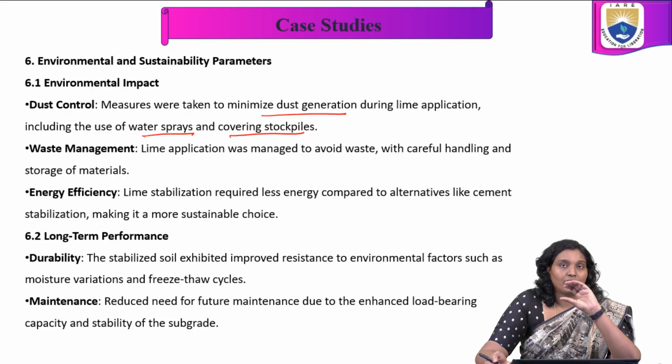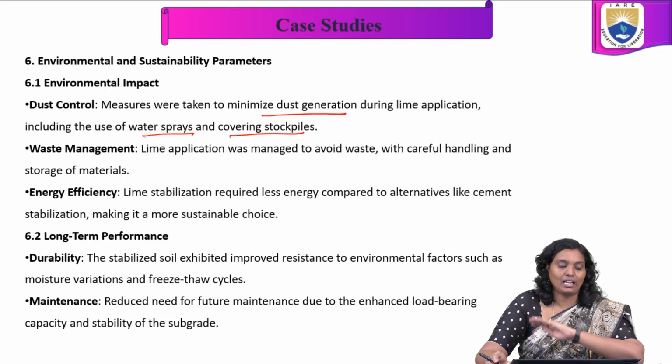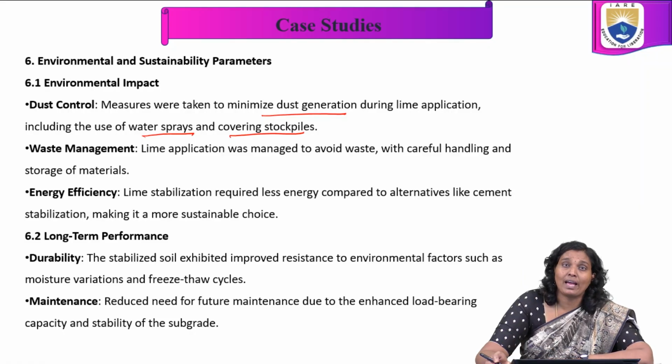As a part of dust control, we did this, and it reduces the environmental impact. In waste management, lime application was managed to avoid waste with careful handling and storage of materials. In energy efficiency, lime stabilization required less energy compared to alternatives like cement stabilization, making it a more suitable choice.